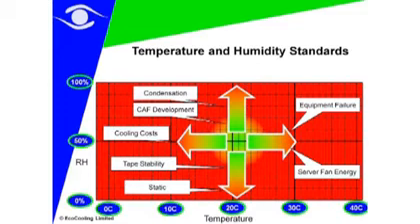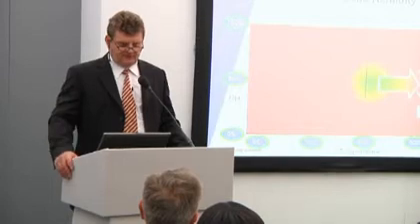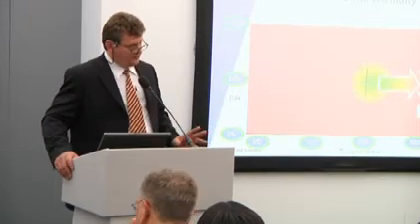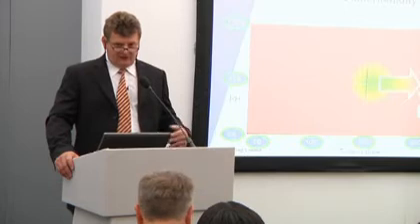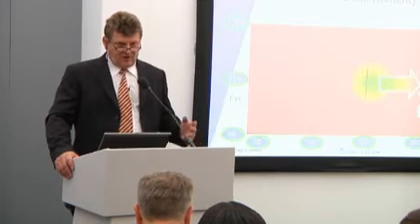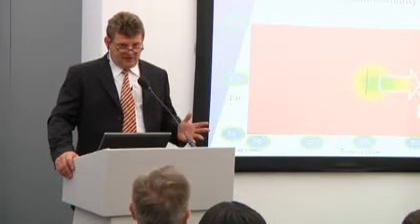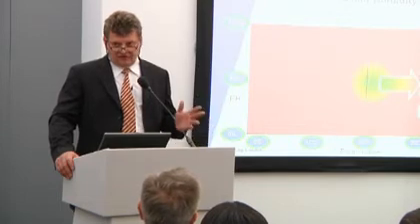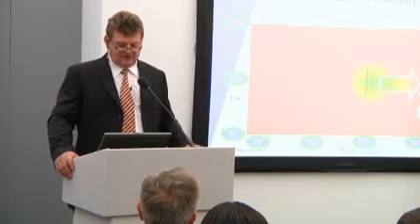That's what people have been brought up knowing and believing. Why? Well, we know if we increase the temperature, we'll start to get equipment failure. Things will blow up at high temperature. What a lot of people don't appreciate is if you increase the temperature of air going onto a server, the little fan starts to speed up and can consume an enormous amount of energy itself.